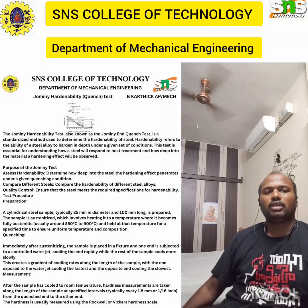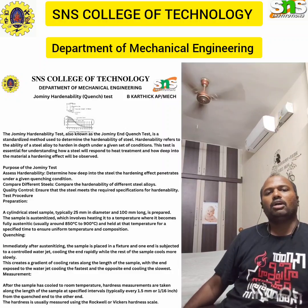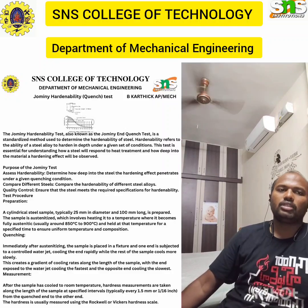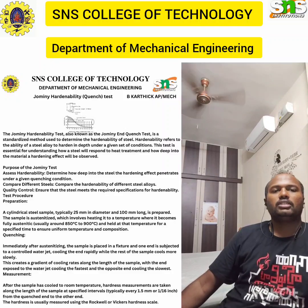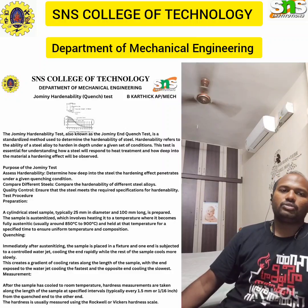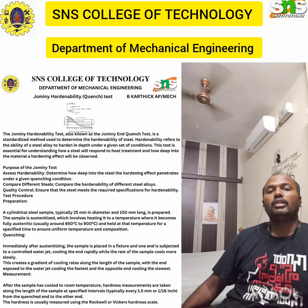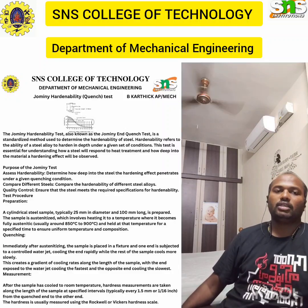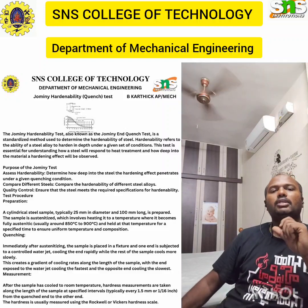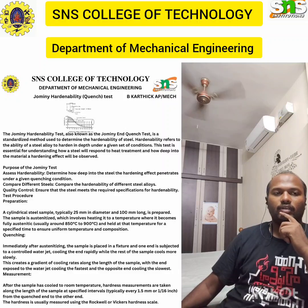So this is another one. Here we are going to see the Jominy End Quench Test. The Jominy Hardenability Test is also known as the Jominy End Quench Test. It is a standardized method to determine the hardenability of steel. Hardenability refers to the ability of a steel alloy to harden in depth under a given set of conditions. The test is essentially for understanding how the material will respond to heat treatment and how deep into the material a hardening effect will be observed.